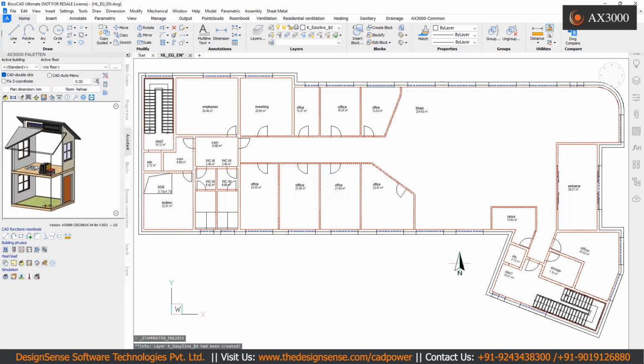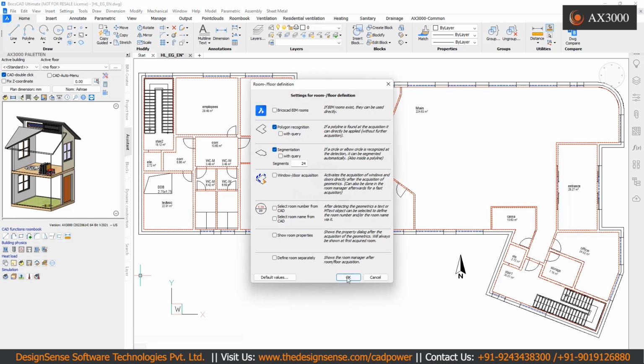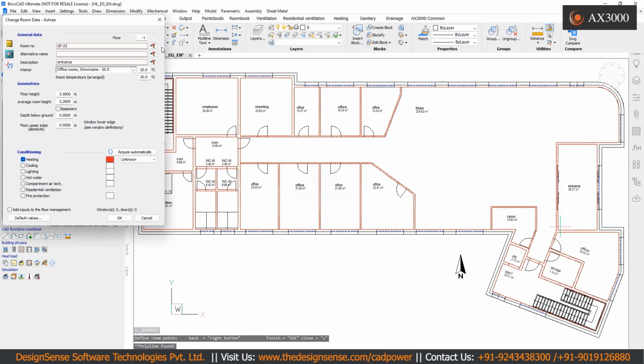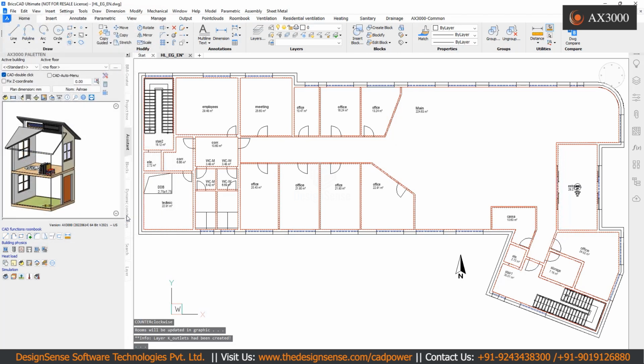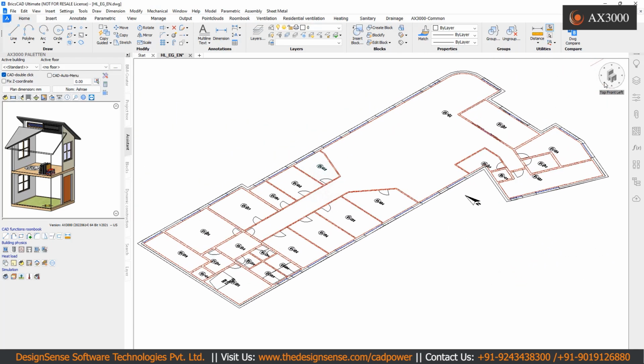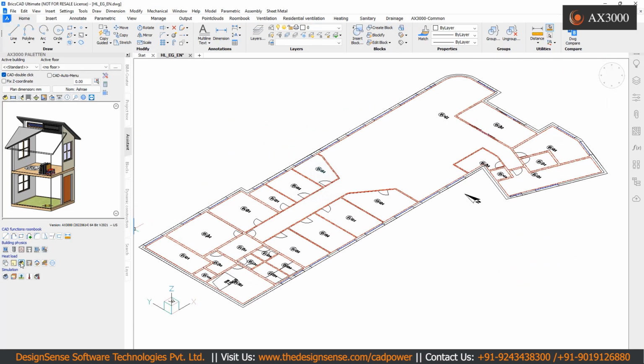The second step is to create the room books, and there are different versions to do this. The simplest way is to use polygons existing in a 2D drawing. We activate the function, select the polygon and insert the values of the room like room number, name, description, height, and so on. This can be done for all of the polygons, so I get as a result a room book per polygon, so one room book per room.